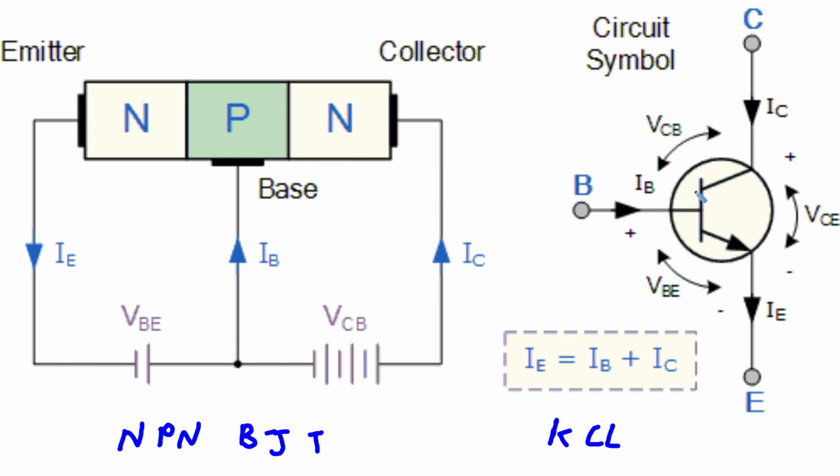This simple equation is the cornerstone of all BJT circuit analysis, perfectly summarizing how the currents within the device are related, and reinforcing the concept that a small input at the base can control a large output at the collector, making the transistor a powerful amplifier or a fast-acting electronic switch.